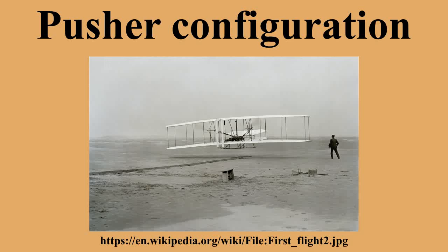When a propeller is mounted in front of the tail, changes in engine power alter the airflow over the tail and can give strong pitch and yaw changes. Propeller ground clearance and foreign object damage: because of pitch rotation at takeoff, propeller diameter may have to be reduced and/or landing gear made longer and heavier. Many pushers have ventral fins or skids beneath the propeller to prevent the propeller from striking the ground, at an added cost in drag and weight.